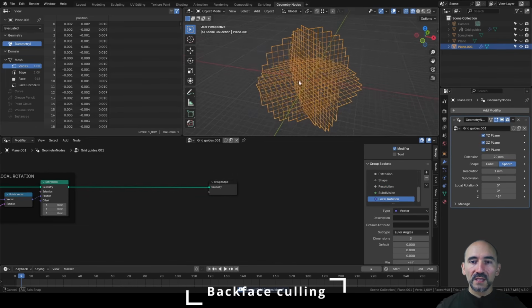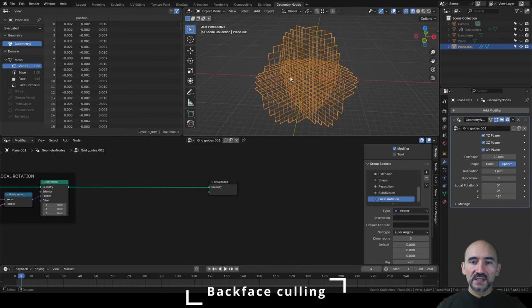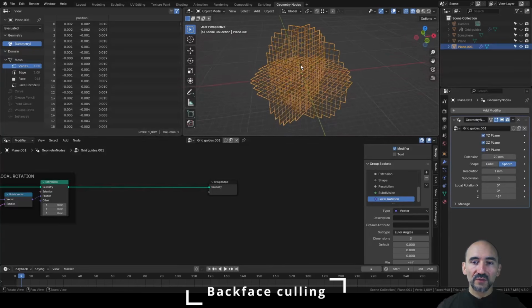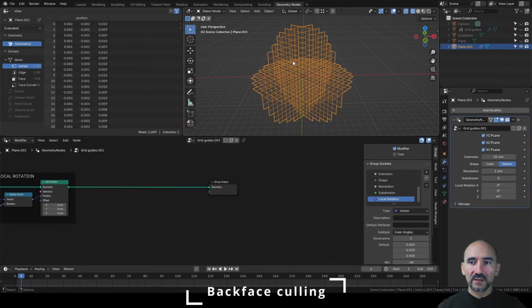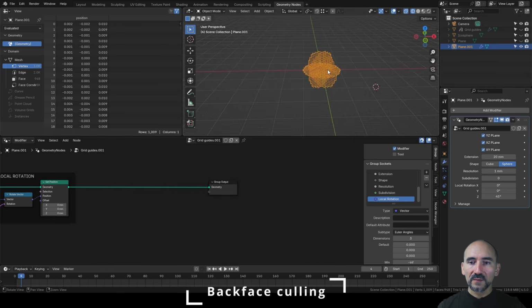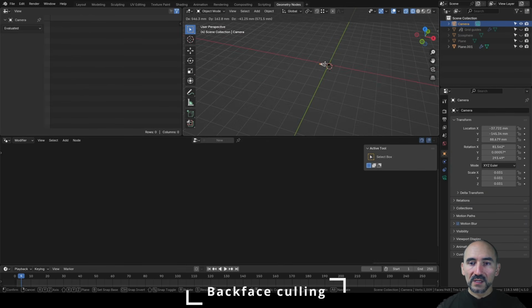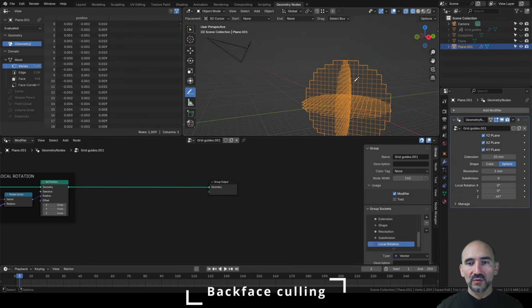Now the tricky part, the hiding and deleting of the faces behind and the points behind from the point of view of the camera. To understand this trick, I enable for a moment the camera so we can see it, and I move this a little bit because the idea is this. Imagine to create a ray that starts from each point of our geometry and goes through the origin point of the camera. For example, for this point we have this ray, for this point we have this ray, but not only for these 2 points but also for the point behind that we want to delete, we can start with a ray through the camera.